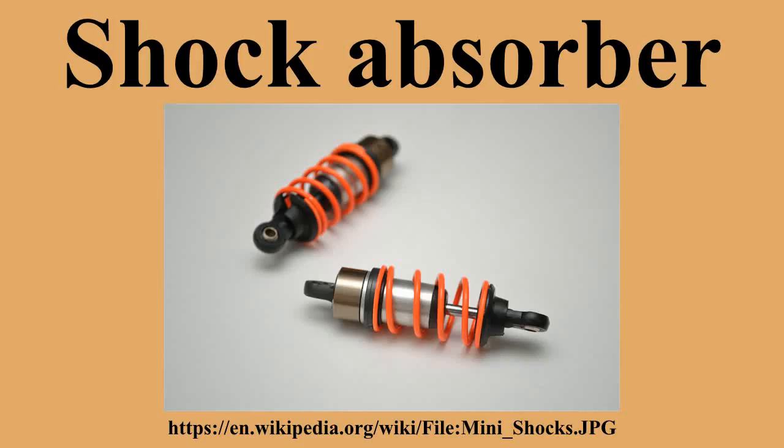One of the earliest hydraulic dampers to go into production was the Telesco shock absorber, exhibited at the 1912 Olympia Motor Show and marketed by Polyphoto Carburetors Limited. This contained a spring inside the telescopic unit like the pure spring-type shock absorbers mentioned above, but also oil and an internal valve so that the oil damped in the rebound direction.